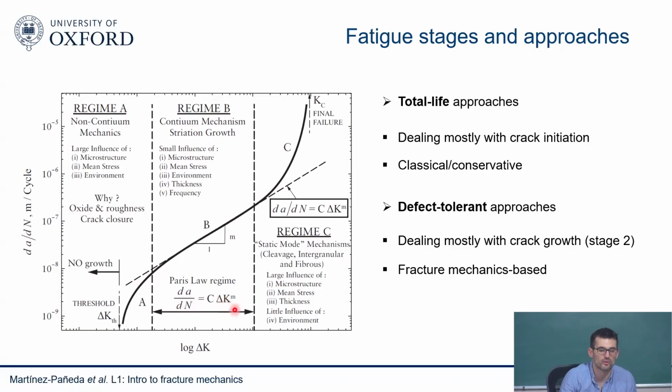K is a stress intensity factor, so there is some sort of fracture mechanics principles in there, but what are C and M? These seem like fitting parameters, out of the blue, there's no mechanistic understanding. Even though it includes some fracture mechanics, it was thought to be a bit too empirical. So it was rejected by all journals.